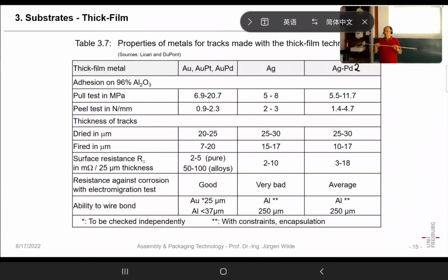That's the ohms per square, because when you make the square bigger, it is longer and is also wider. And in that way, resistance always stays constant. So that's why these people typically use ohms per square, because they don't know the cross-sectional area.